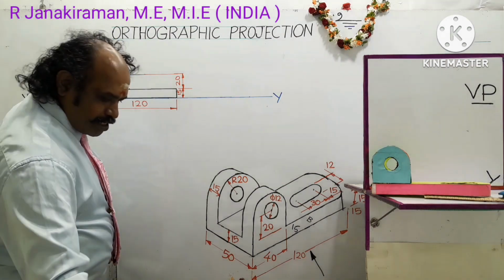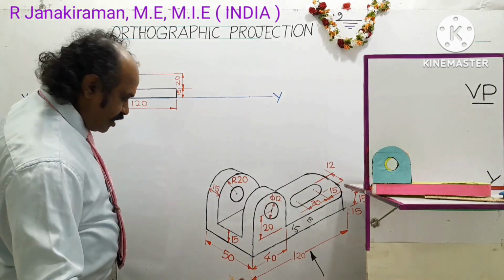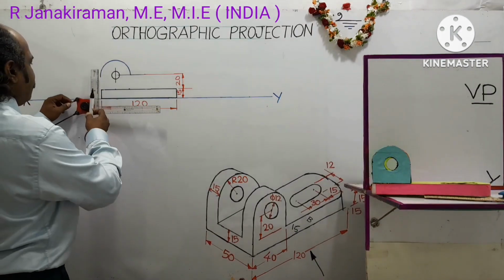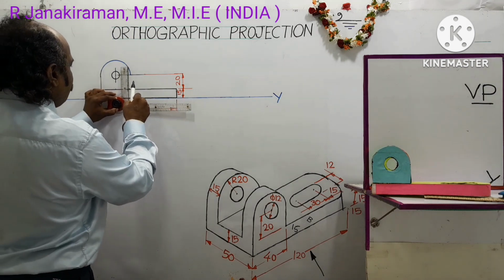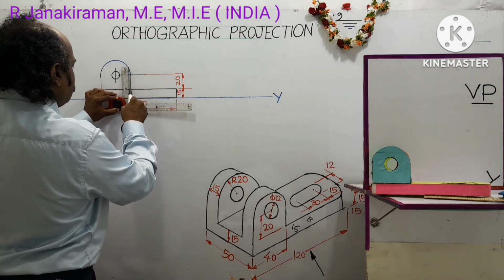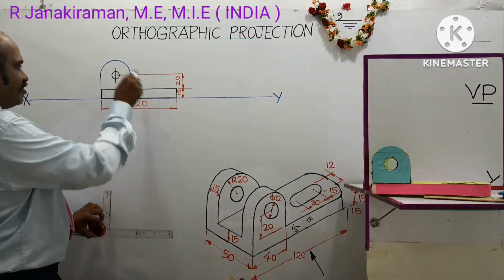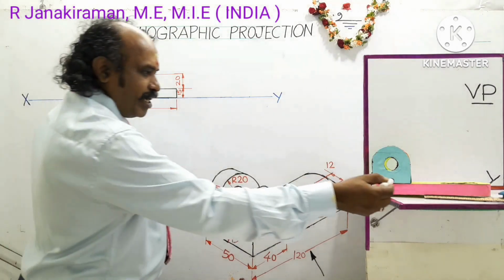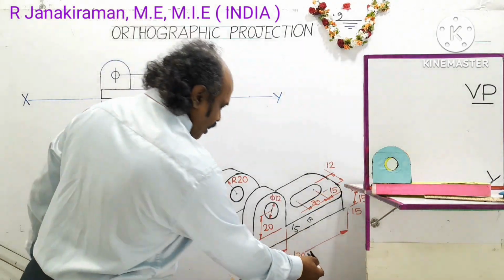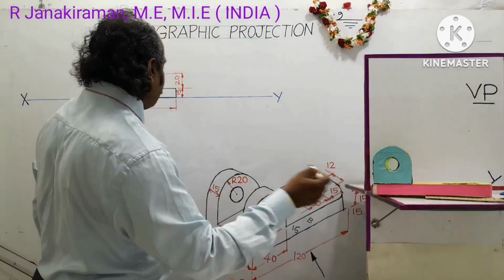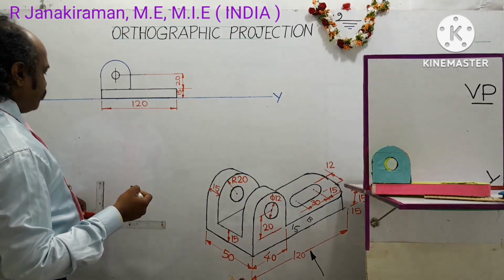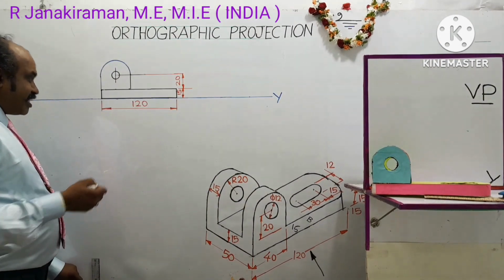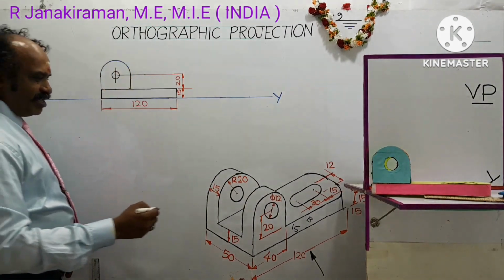Okay, and using the vertical scale of your drafter, join with the base. So this completes the elevation. Another name for elevation is front view. This is the view obtained. According to that arrowhead direction, this will be the front view. It's drawn on the marker board. Same principle when you draw it on the drawing sheet. So next we will dimension the circle and this arc, referring to the diagram.